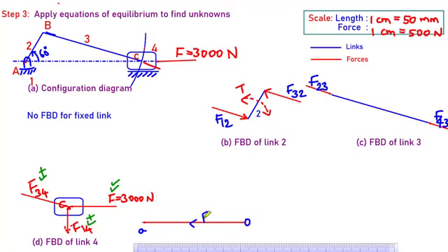This is the applied or external force F. So I have used this data. I do not know the magnitude of the two remaining forces, but I know the direction. From end A, I have to draw the next vector. It's a vector addition, so I can take F34 or F14. Let me take F14. Do I know the direction? Yes. Magnitude? No. So I simply draw a line to some approximate length. I don't know whether it is upward or downward; right now I am assuming that way.